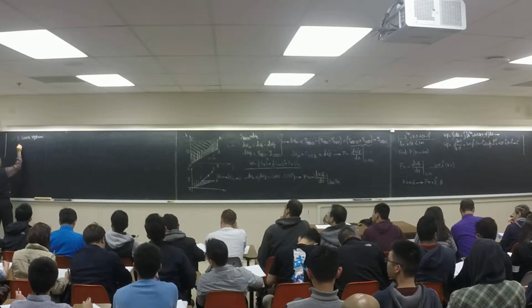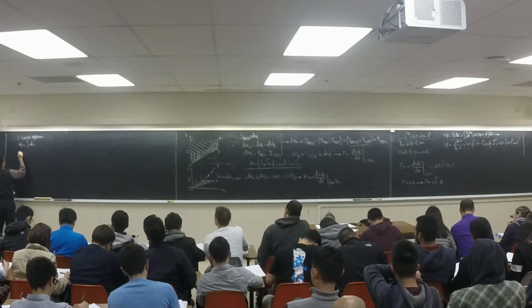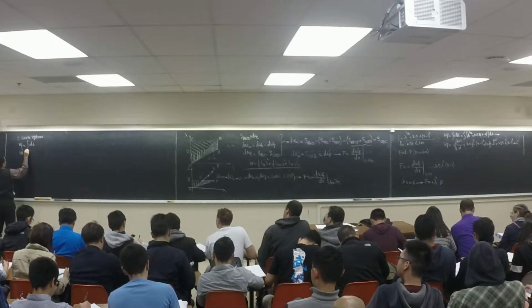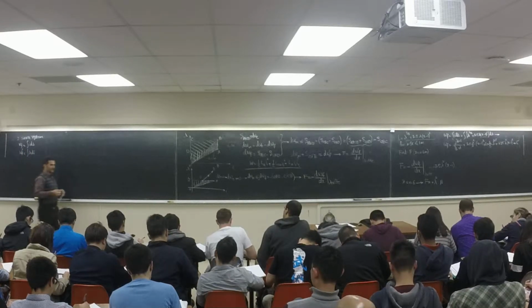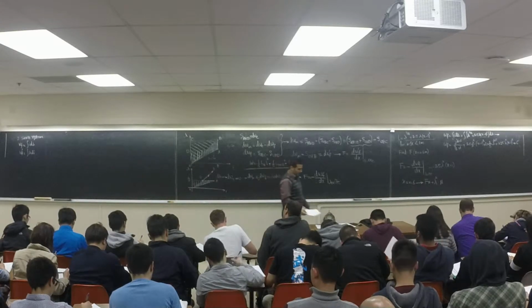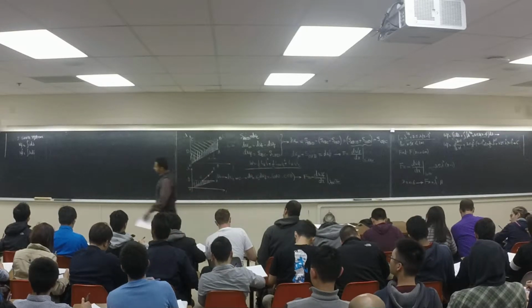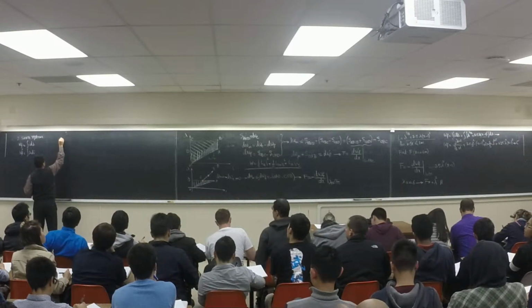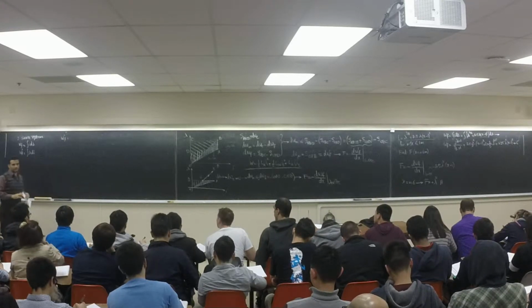Again, we remind here W_f is the integral of i dλ, and W'_f is the integral of λ di. Now we have a two-source system. There is a λ1 i1 and there is a λ2 i2. Let's see how we're going to solve this. Co-energy. I want to calculate the co-energy. W'_f is going to be equal to